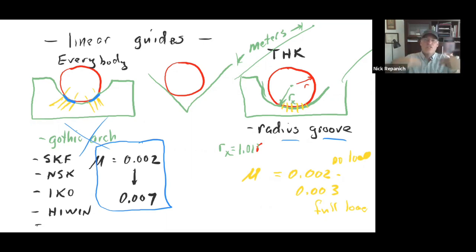You do that several iterations, and pretty soon you get to really good flatness, and the groove was very controlled and didn't undulate. And that was their key to being able to make these radius groove bearings.